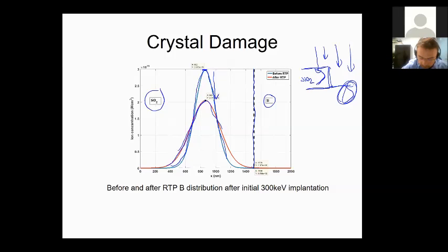They may propagate so much that they will start leaking under the silicon. So again, it might defeat the purpose. We might introduce a significant contribution. Well, I look at the concentration, so there's not a big worry. I will just read them for you. Before the diffusion, it's 2.97 times 10 to the 10 per centimeter cubed.